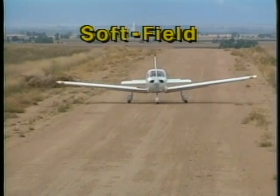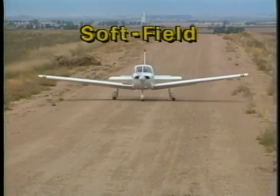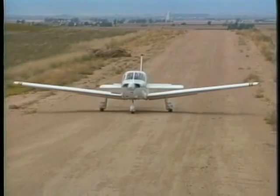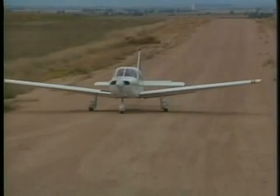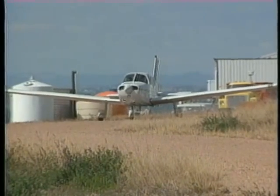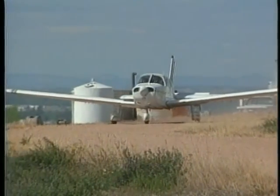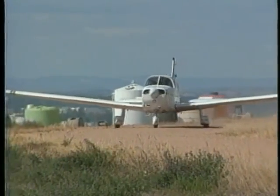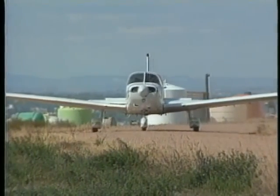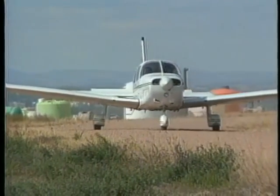Soft field techniques must be used when the runway surface is covered with snow, sand, tall grass, or mud. You may also want to use these same procedures to minimize the problems associated with a rough surface. If the taxiway is also soft or rough, the soft field procedure actually begins in the parking area. Plan ahead so you can keep the airplane rolling once you start taxiing. This might mean you will have to complete the pre-takeoff checks in the parking area. Once you begin to taxi, keep the airplane moving at a steady speed.